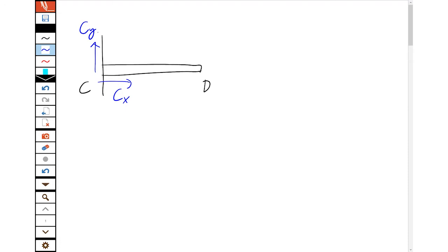And it can't rotate, which means there's a moment reaction at C. So there's a moment at C. And remember again, it's very convenient just to assume that these are all in the positive directions. It makes our math handier. And again, we can do the equilibrium equations on this beam to work these out. At D, there's no reaction because it's not touching anything.